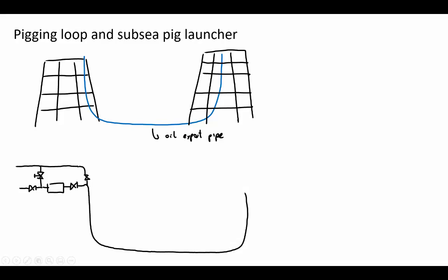So this valve has to be closed, you open here, and you insert the pig in this chamber. You put the pig here.